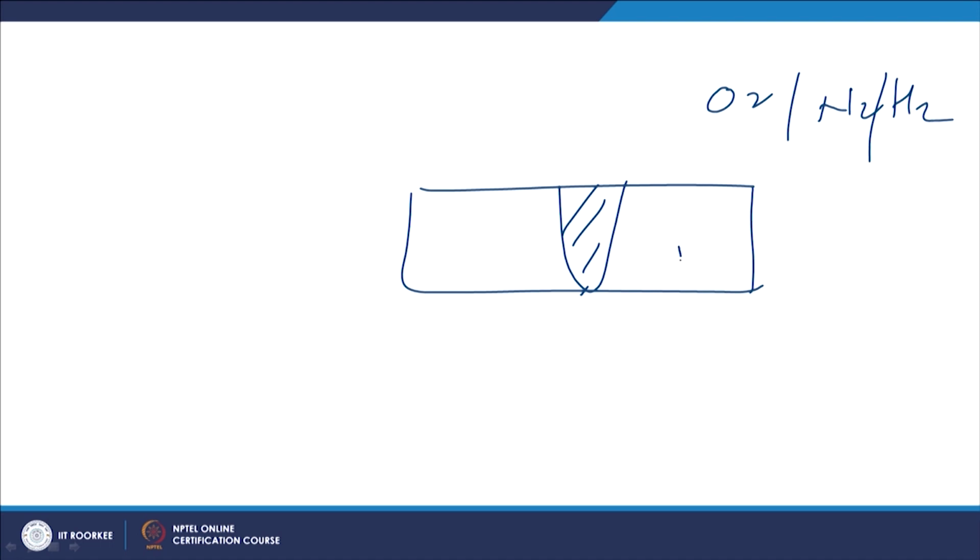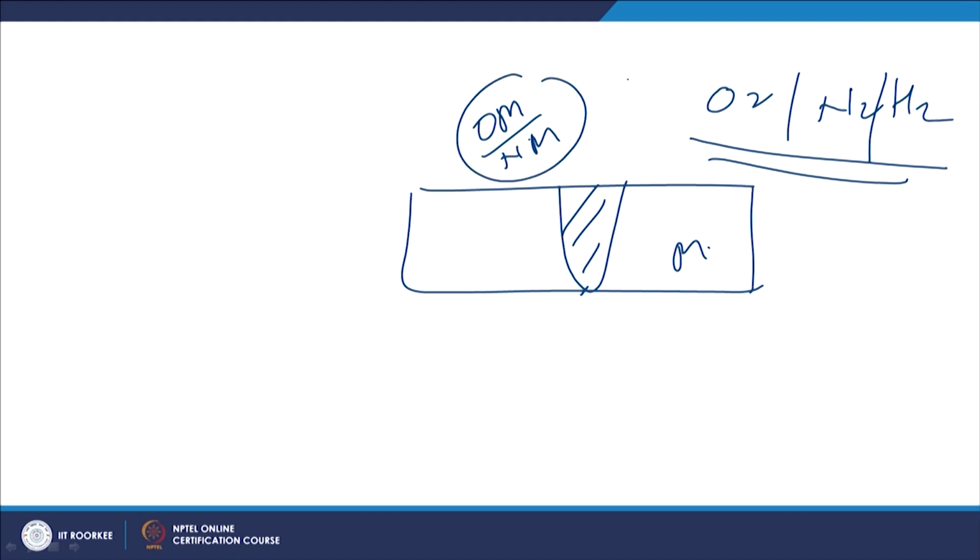The way by which the metal has an affinity to these gases which are present all around during welding can lead to the formation of oxides or nitrides of that given metal, and these oxides and nitrides may be refractory in nature. These may be hard and brittle, and may interfere with the fusion of the metal. So, these will make the welding difficult.